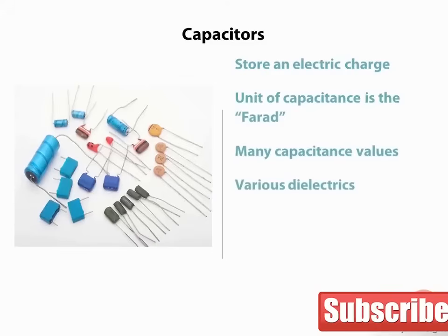Capacitors are often classified by what their dielectric is. Common materials are ceramic, mylar, paper, or even air. The dielectric is selected by the application of the electronic circuit. Different dielectrics have different costs. A ceramic capacitor is quite inexpensive when compared to a mylar capacitor. In digital circuits, the ceramic capacitor may be adequate, but in audio circuits, we would opt for the more expensive mylar capacitor because of noise concerns.